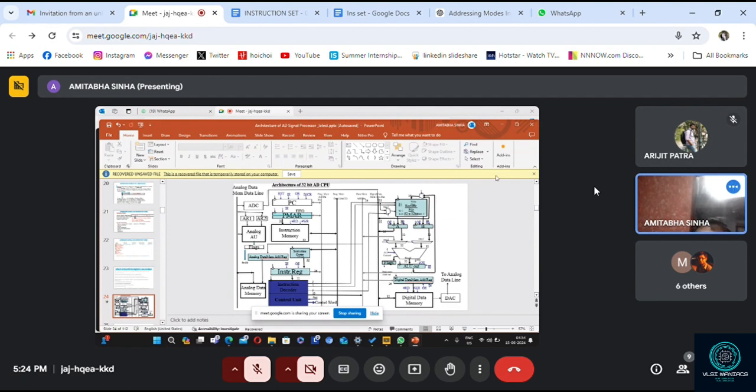So we need all these devices. But unfortunately, when we design VLSI circuits, making an inductor is not a trivial task. It will take huge area and huge power consumption. It is practically impossible to implement an inductor within a VLSI chip. So as designers, we find some indirect technique to use the inductor.